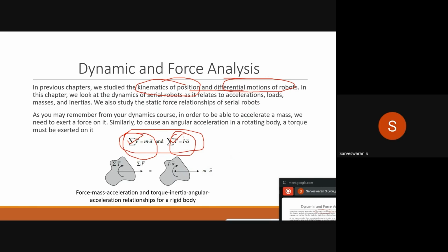In simpler terms, for prismatic joint movements we calculate the force component, and for the rotational component, that is revolute joints and others, we solve for the required torques to rotate the links. In our robotic arm, mostly the joints are revolute joints, and we will talk about how to arrive at a suitable torque for the robotic arm.